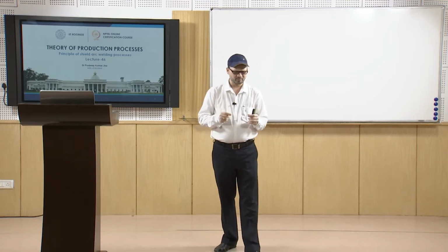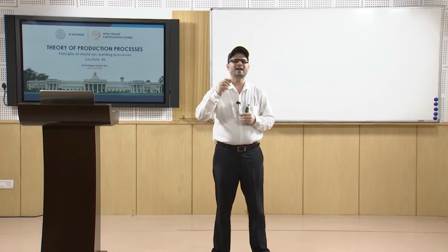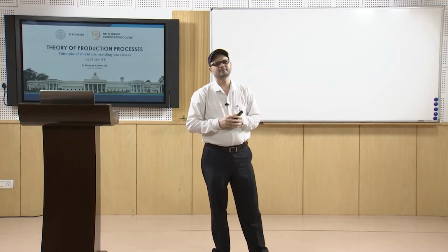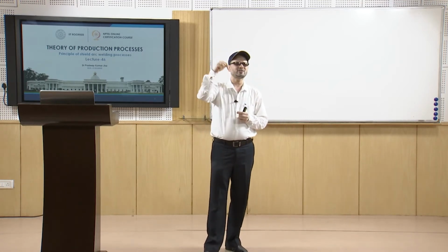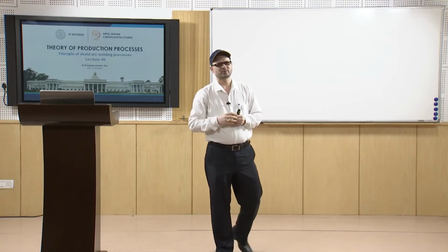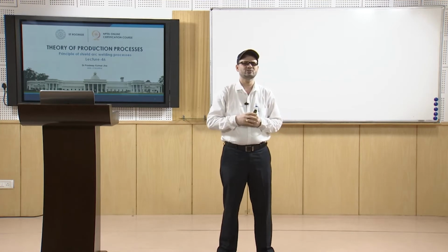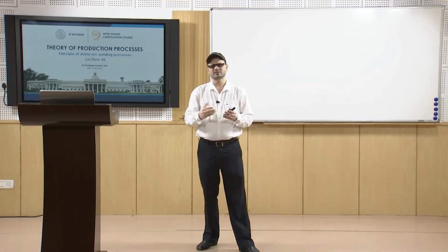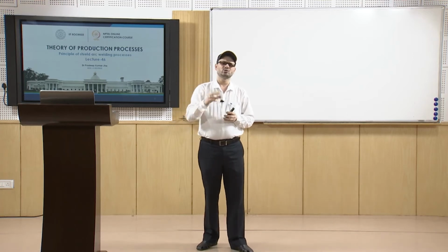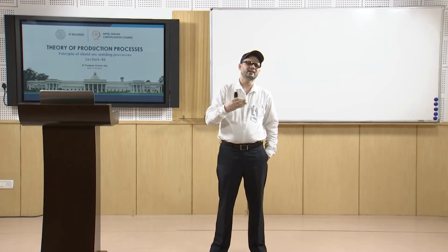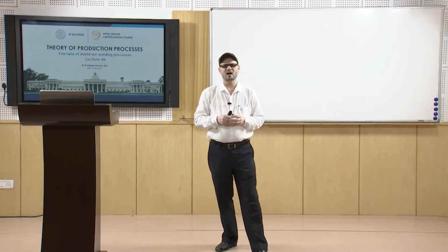This is a tungsten electrode, and you feed the required material in bare form, and the shielding is done by supplying gas. You have a specially designed torch, so the gas comes, and the gases normally used are helium or argon, and in some cases carbon dioxide also. But the tungsten electrode is there basically to create the arc.